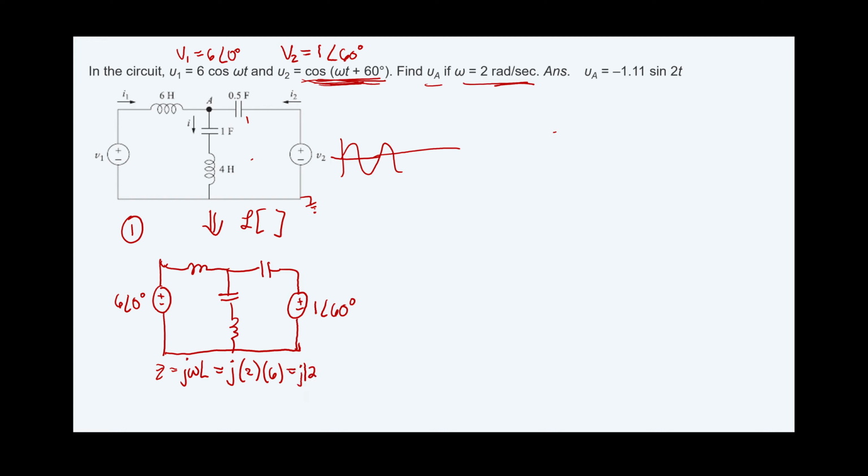You can treat this one as a resistor. If you remember from the first part of this class, you have a simple DC resistor. You might as well use the same idea, but this time instead of a resistor, you simply replace it with j12.